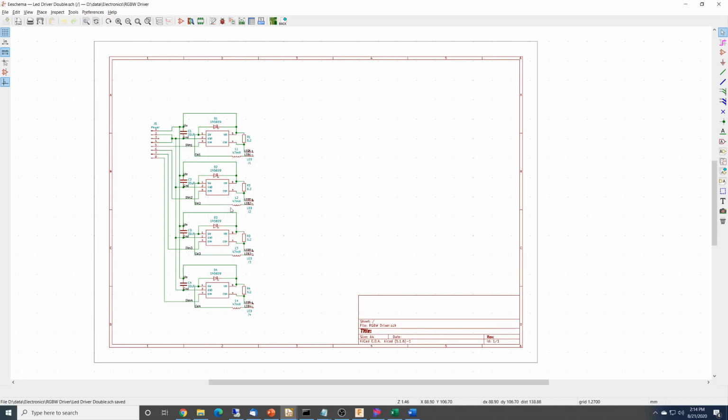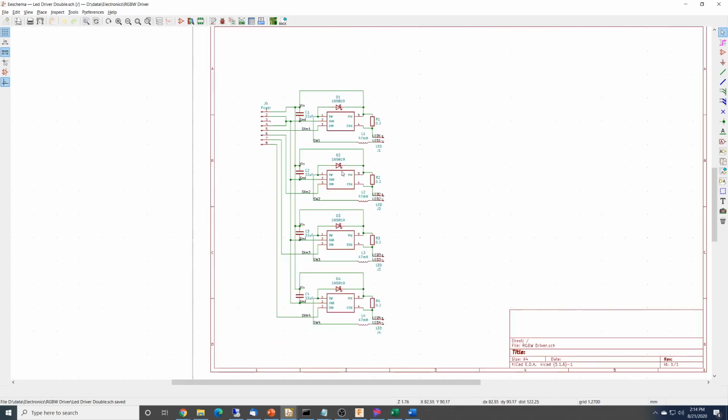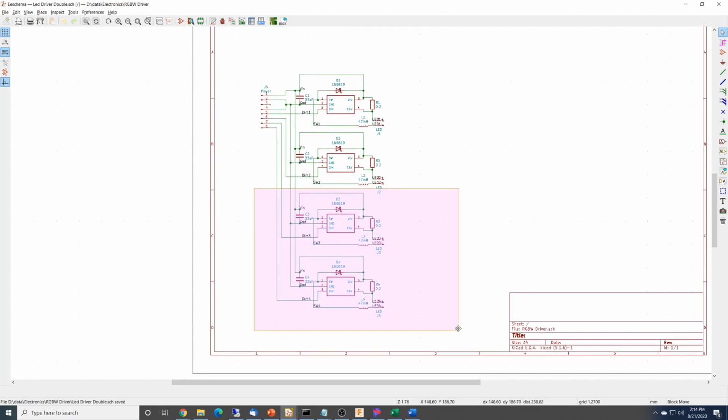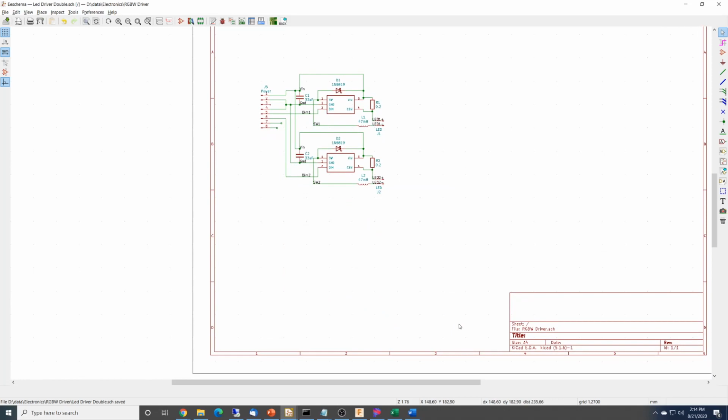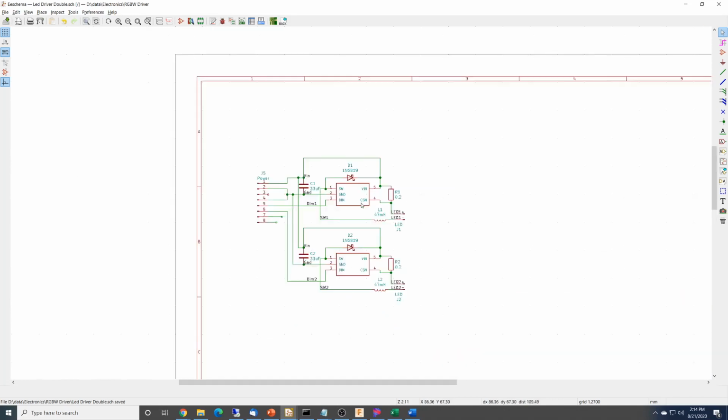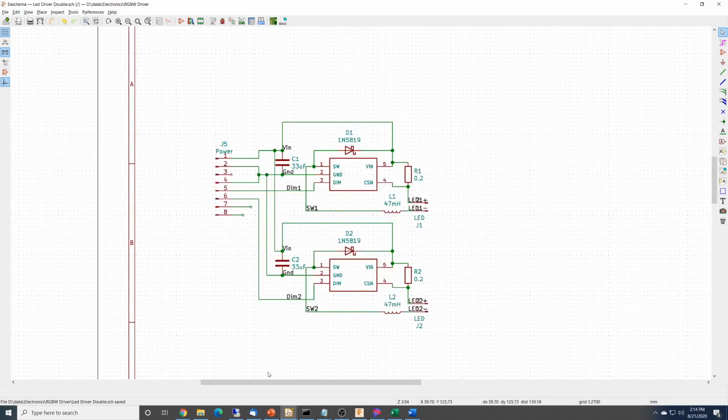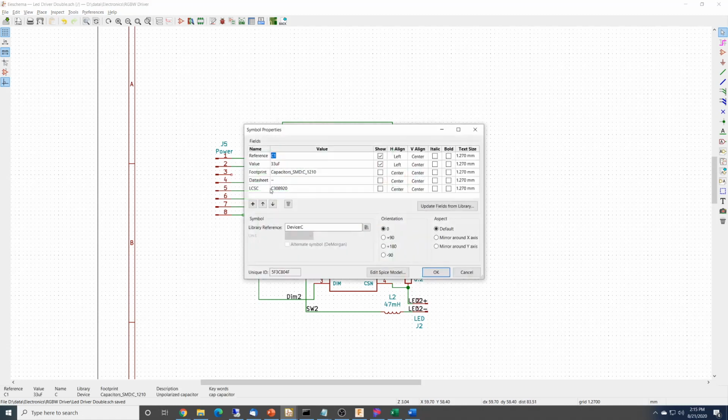And you can see I have 4 examples here. So what I can do, selection is really weird in the schema editor in that it doesn't really show up the way you'd expect it to. So all I did is do that and selected all of those. And now that I've chosen a new capacitor, I'm going to make sure I don't forget that. So go over the capacitor, hit E. This is the LCSC part number of the old capacitor that I was using. So we're going to replace that.